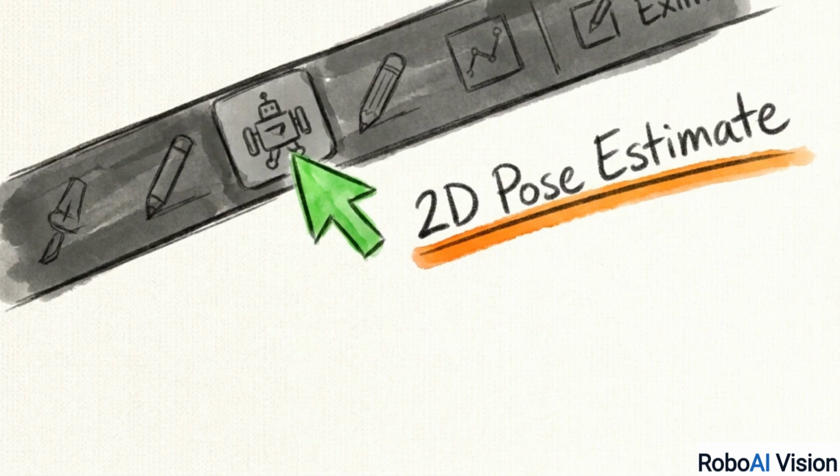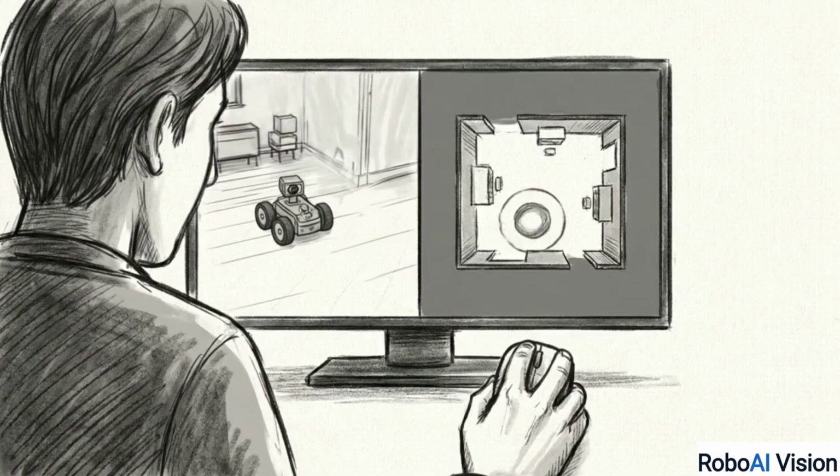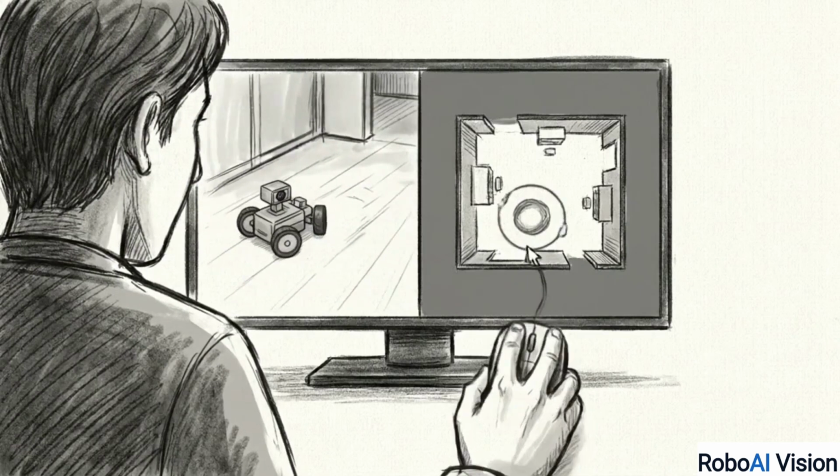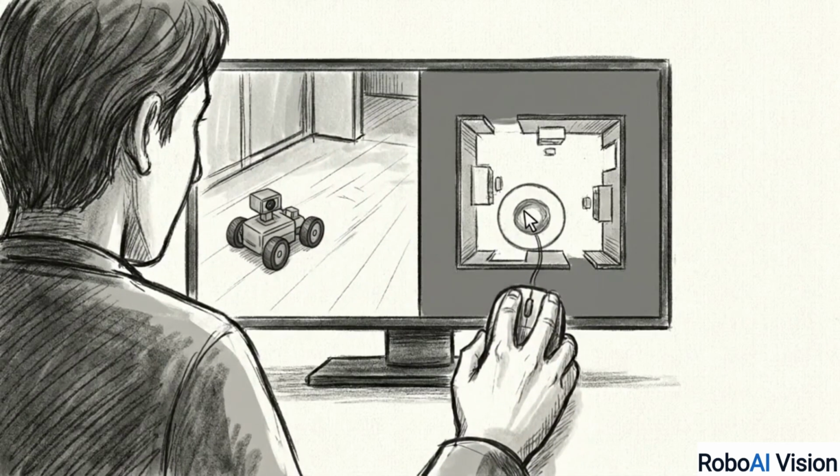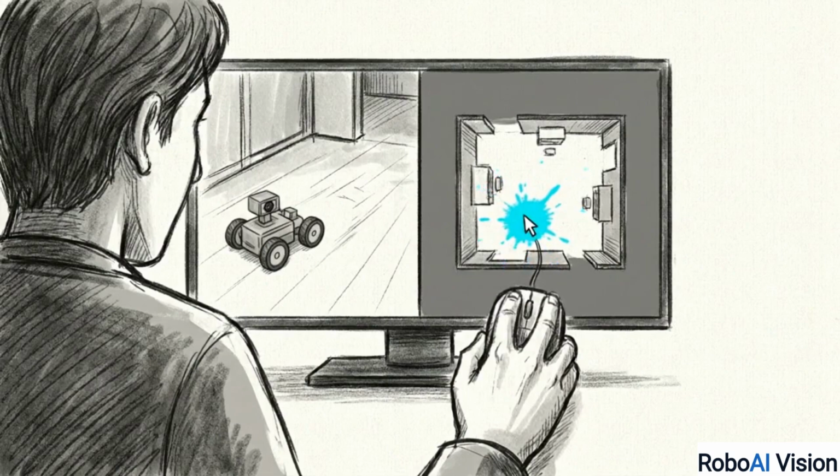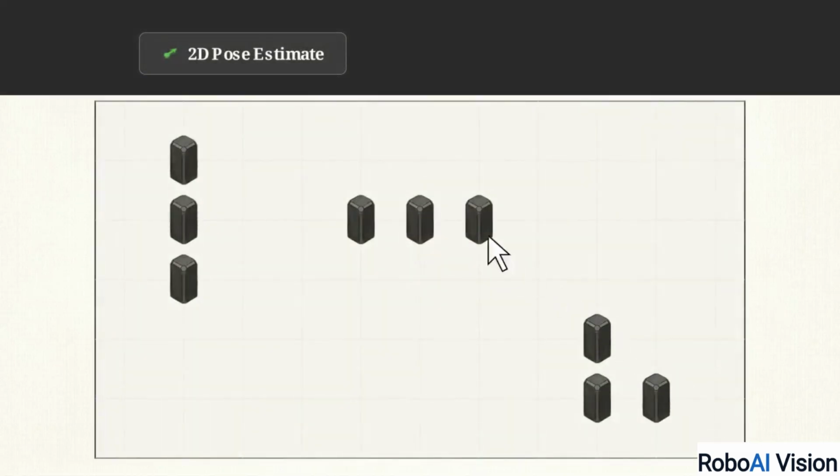We provide this initial estimate manually using ROS2. This demonstrates that even automated pipelines often require a human-provided starting point to successfully link the digital map to the physical world. To seed the system, navigate to the top toolbar in RViz. Select the 2D Pose Estimate tool. Click on the map at the approximate location where the robot is currently positioned. While holding the click, drag the cursor to indicate the direction the robot is facing, setting the theta value.